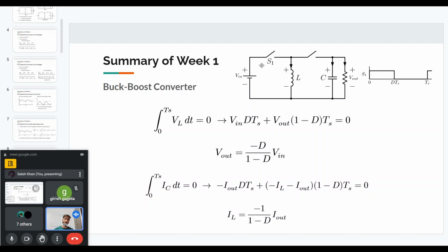So that is the switch analysis you can do, and then you can also find out what will be the ripple current and ripple voltage in the capacitor and inductors. So a number of things you can do, and then you can also find when this kind of a converter, which does not have bidirectional switches, which has a diode and some other switch, when that converter will go into CCM and when that converter will go into DCM.